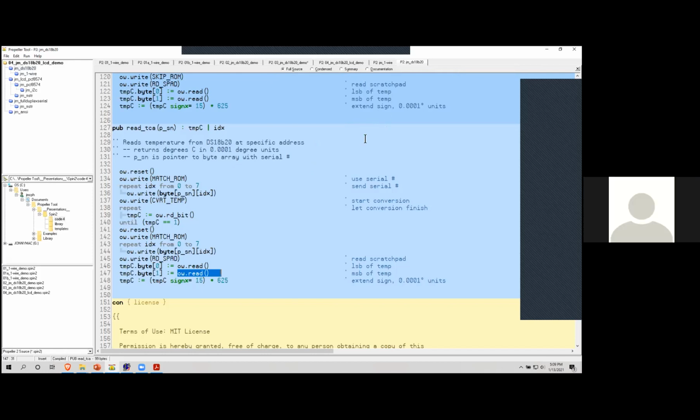You know, John, whenever I was studying the OneWire, like the last gentleman said he was having problems reading multiple devices. One of the application notes says that you can run into that problem with multiple devices. So they actually have a booster circuit that you could build for boosting the 5 volts, because I think they said that was the biggest problem with multiple devices. It was a little circuit that just boosted power on that bus. Well, if you're doing parasitic, yes. And one of the things that I tend to do is use a stiff pull-up.